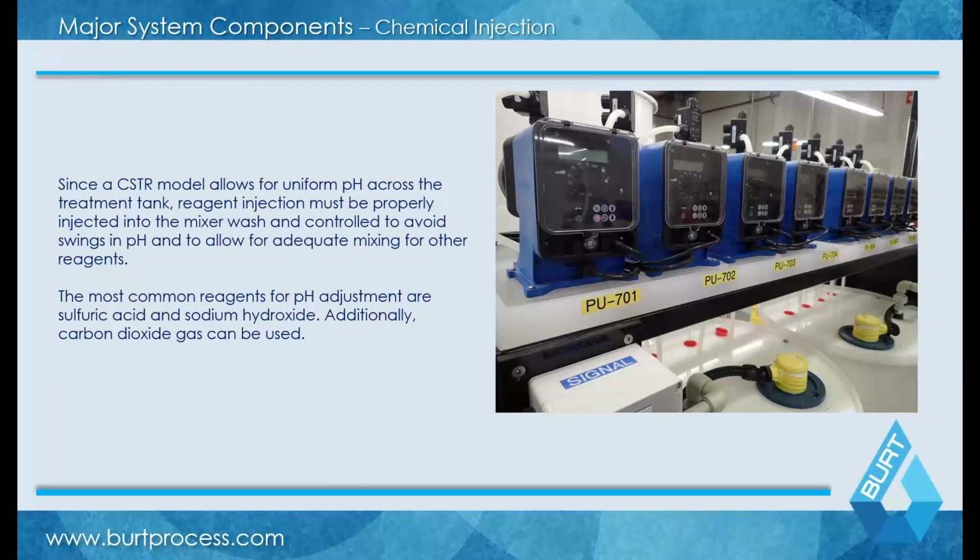Moving beyond the pH neutralization tank, you do have your chemical injection. And this is really what you're injecting to neutralize the waste coming into your system. Again, looking at the pH scale from before, you have a pH range of, say, 0 to 14. Realistically, most pH neutralization systems operate in the range of 2 to 13, or 1 to 13. Once you get beyond 13 to 14 or into a 1 to 0 range, you can treat it, but you obviously have to treat it as a special waste consideration.